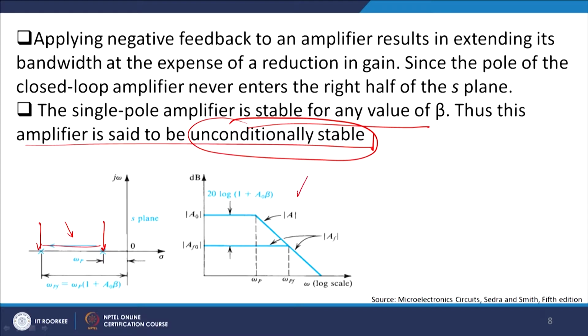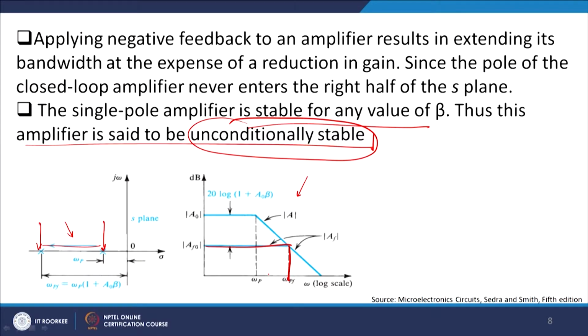On the right hand side, if you look very carefully, it is a plot of gain versus frequency, and as you can see, as the gain falls down, its 3 dB bandwidth, basically the higher cutoff frequency, which is this one, is actually rising, right. So gain into bandwidth product again is constant, which is the standard rule of thumb we apply in reality. Now let us look at a 2-pole response or a 2-pole design, and I will explain how a 2-pole design works typically in this scenario.